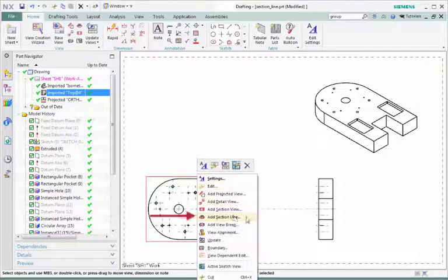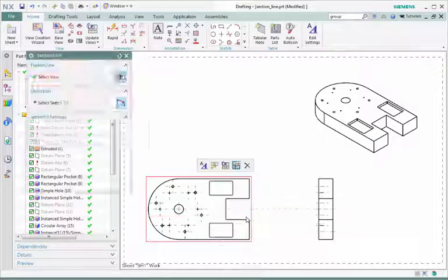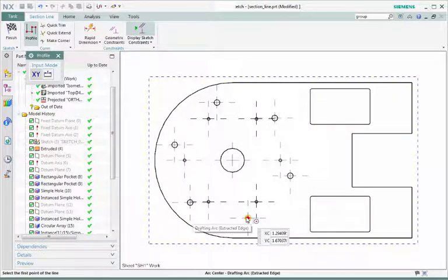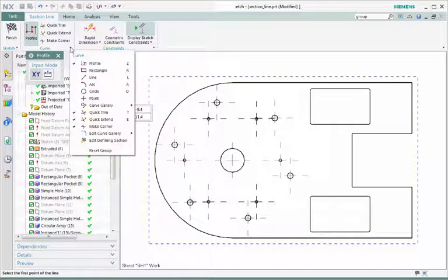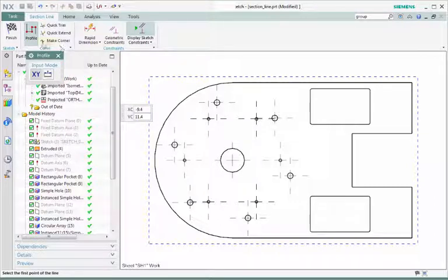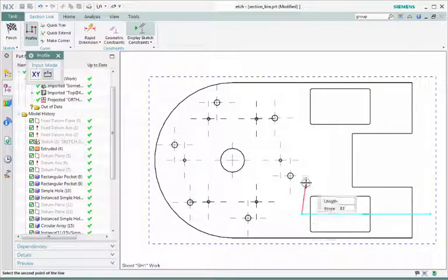it here. Then you enter the sketch task environment with the familiar tools in the ribbon bar. It's a little more streamlined than normal, but all the tools are available. You can have only one continuous section line, which is why the most logical sketch curve tool is the only one that displays by default, Profile. I'll use it to create my section line.